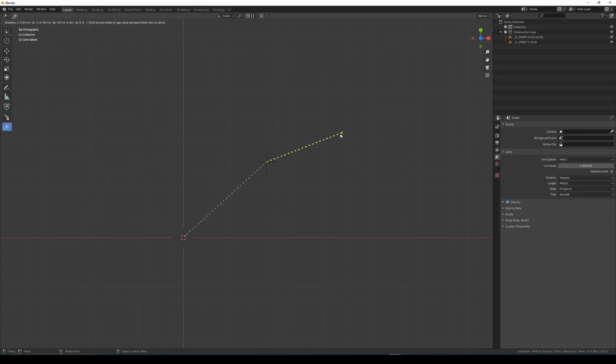So I've changed this now, that when you want to enter numeric input or some expression, you will press the enter key, which will enter a new mode now, an input mode, and you'll see that because it says up here type in number or expression, and then you can simply type in your number either on the number pad or the number row on the top of your keyboard. They will both work in the same way. I'll type 2 here and hit enter again, and that will work to produce the new geometry or the new guide. And it's a much cleaner, much clearer way of working, I think.